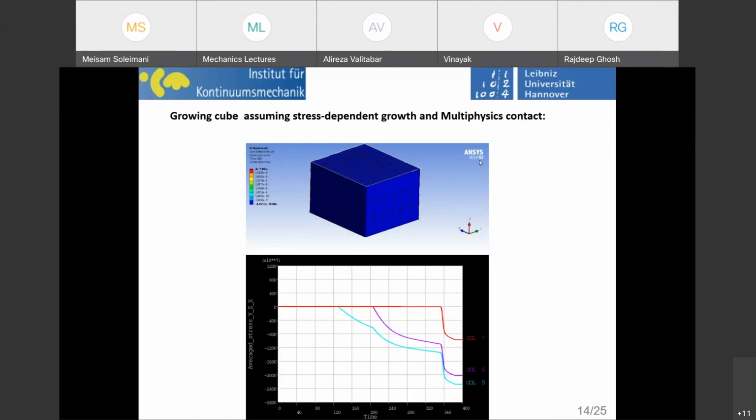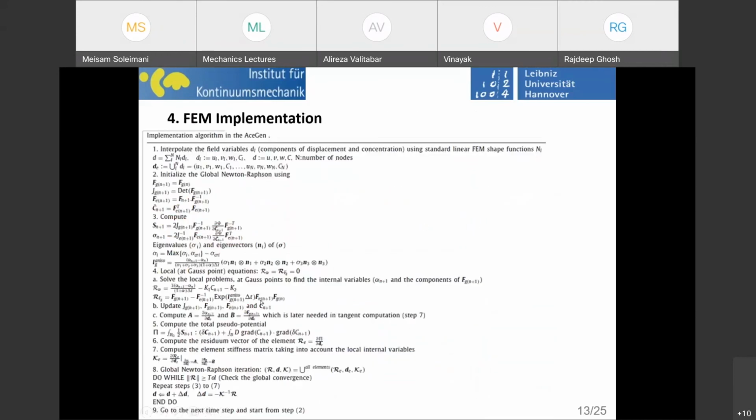But the point is that once all the contacts are established, let's place ourselves in the shoes of those growing cells. So they just grow. From a mathematical point of view, as soon as you take the whole space, since you cannot have an increase in the volume, your stress increases rapidly. And then once you reach that criteria, that sigma critical in the 3 direction, keep in mind that it's a tensorial representation of that. It means that the growth might stop here, but still we have growth in these 2 directions. And then once all of them reach this criteria, then you have the 0 growth.